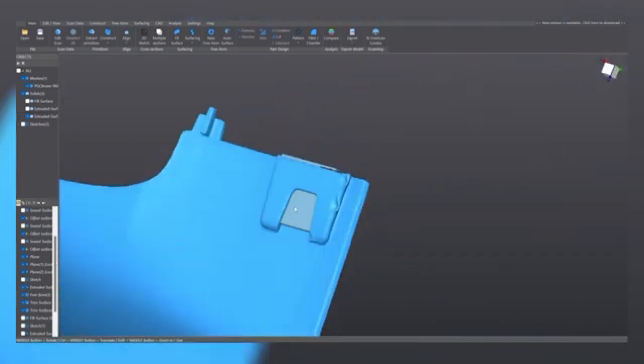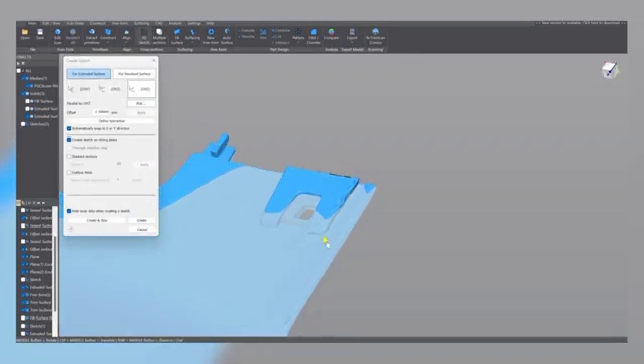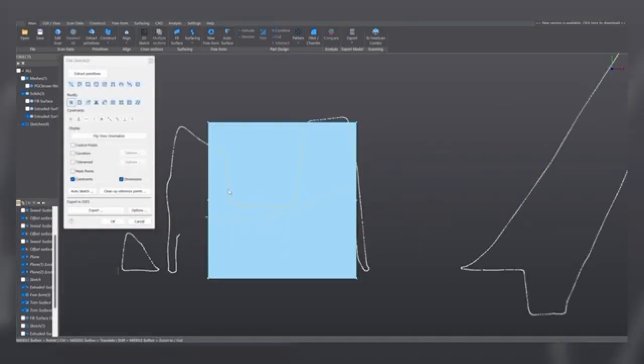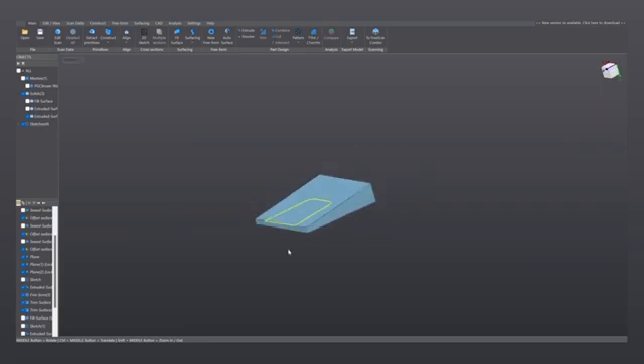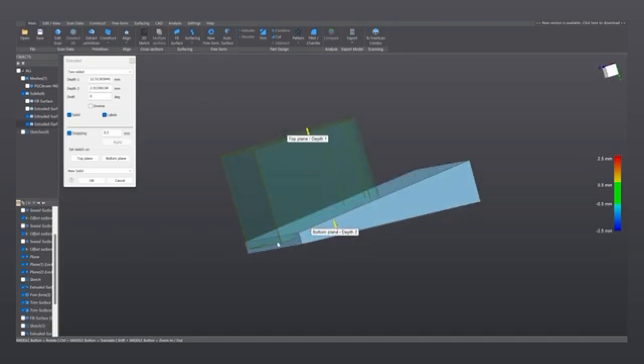And now let's focus on this cutting over here. For this, again, we repeat the process. We select the proper plane and we move the slicing plane accordingly. Great. Again, create sketch on slicing plane is selected. And we best fit these three lines here. We join them. We fillet them. And let's extend these lines beyond this body and close the sketch. All right, now we extrude this closed sketch till a certain height here, and here making sure that it extrudes until it's inside the other body. New solid is again selected, click on OK.